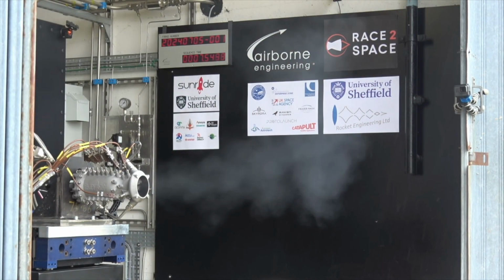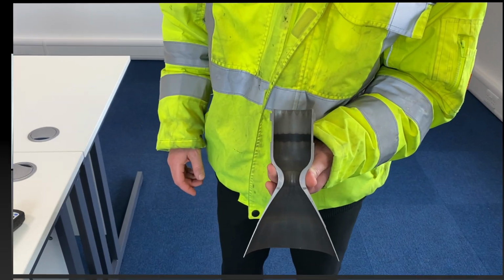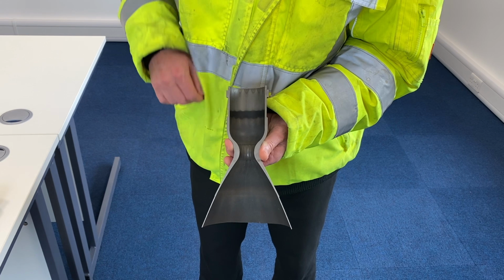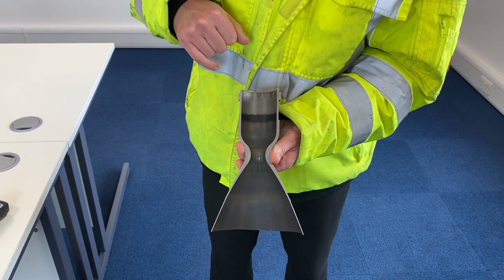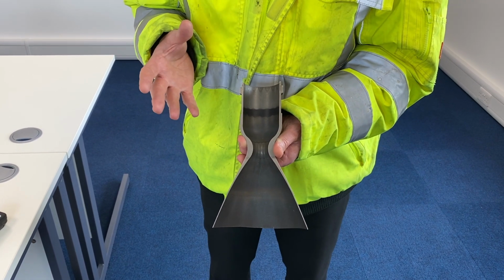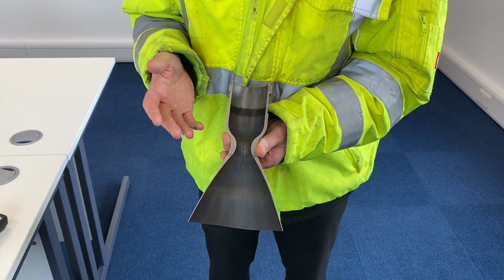Now, Dr. Ian Coxhill, Chief Engineer, Nammo Space, on rocket engine cooling. Okay, Adam, so what you're looking at here is the inside of a Leros 1B engine, and you can see the pattern generated by the fuel film cooling. So these rocket engines operate with a core combustion temperature of about 3000 degrees C, and the melting point of the material is little over 2000 degrees C.